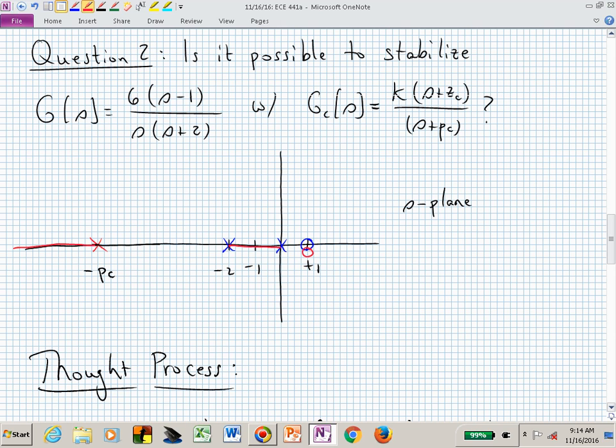Is it clear to you that some of these real line segments might possess more than one branch? And that's where you might now have interesting behavior. What's interesting about the root locus between 0 and -2? What's happening there relative to a rule? How many branches do you have of the root locus between 0 and -2?